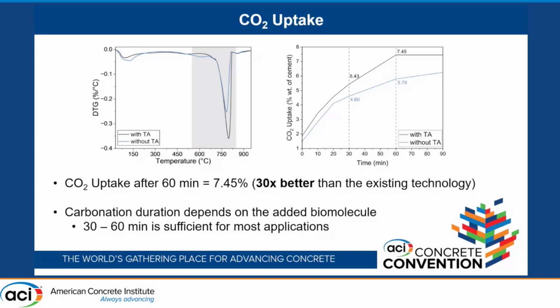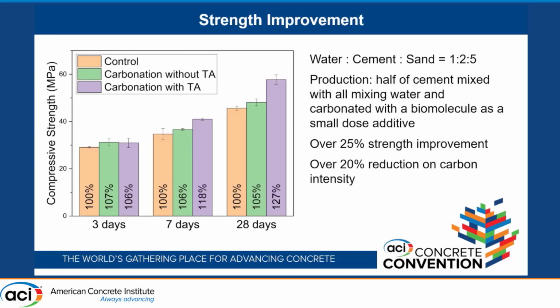But none of this matters if the cement or the concrete just falls apart as soon as you finish curing it. So we need to look at the compressive strength over time. You can see on this graph, we measured the compressive strength at 3, 7, and 28 days. We compared it to our regular control batch in orange, which is not carbonated and does not use tannic acid. And we compared this to carbonation with and without tannic acid.